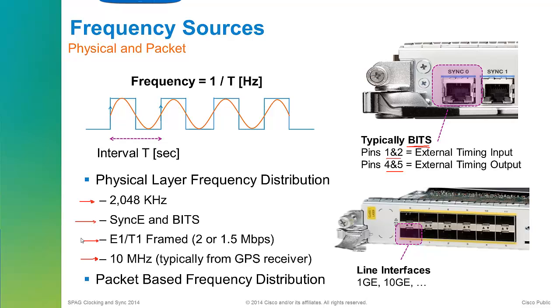So I didn't really cover, what is frequency synchronization and having a source of frequency doing for you? Well, really it's quite simple. All it's trying to do is to say that if you have 10 megahertz, you're at 10 megahertz, you're not at 9.9, you're not at 9.99, you're not at 10.01. That your oscillator that is driving your data circuits is running at 10 megahertz, or whatever it's required to be, 2 megahertz if it's an E1, or 1.544 if it's a T1. And all it's saying is, it's 1.544, it's not 1.55, it's not 1.53, it's actually 1.544.